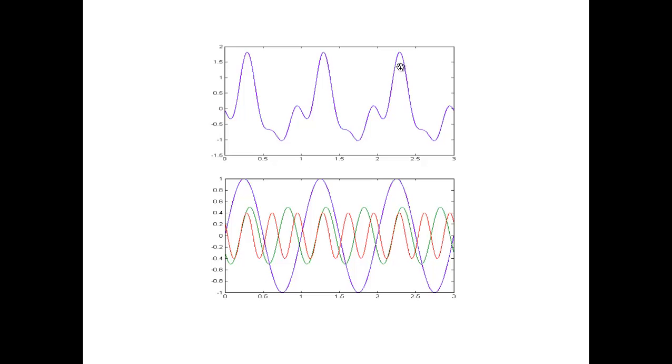But there's a nice way to look at these signals better than just looking at them as a time series. Turns out that this one that I created is nothing more than 3 sinusoids of varying amplitude and phase added together. So here are the 3 down below. That's the dissection of this signal up above. The sum of these things is exactly this.